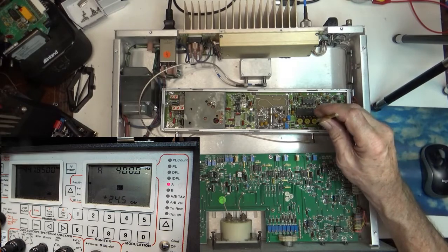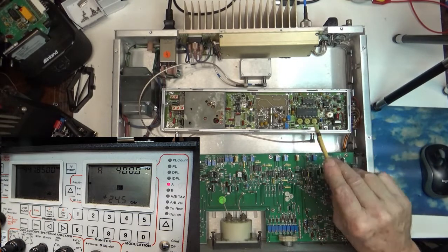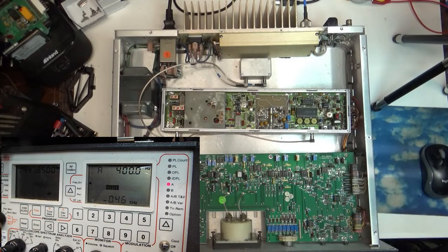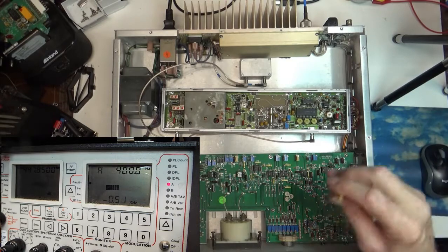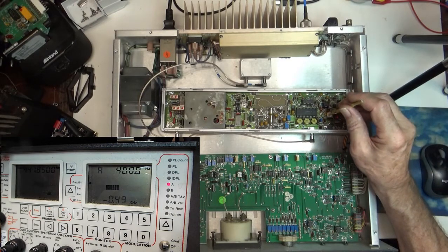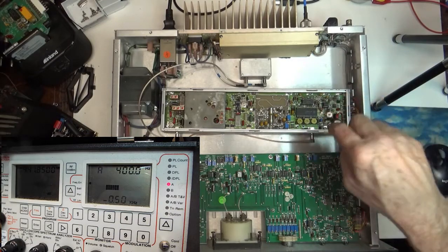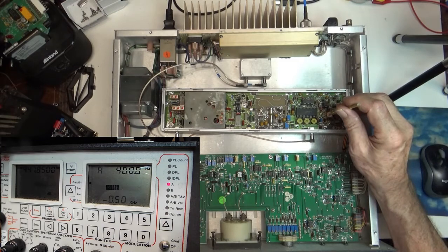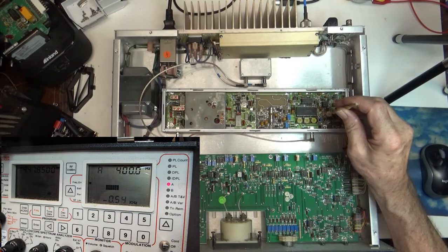So let's take our number 3 here, bump it up 1. So that gives us minus 50 because we were off 5. Well, let's get our little diddling tool right here on the fine adjustment, and very touchy this.